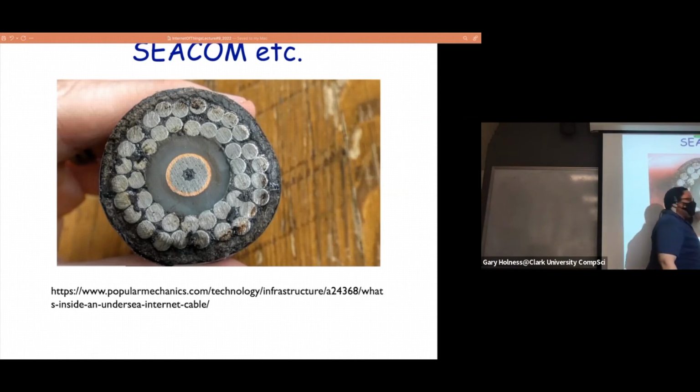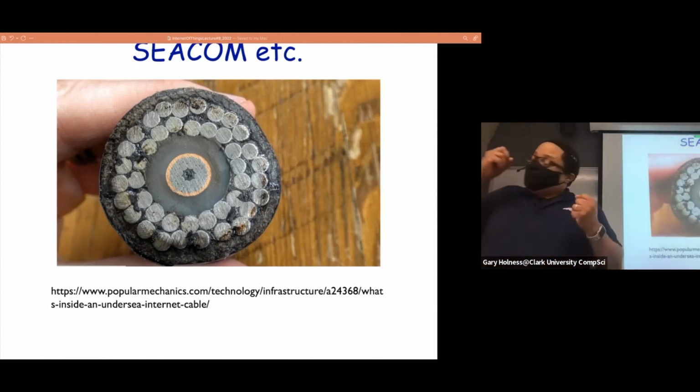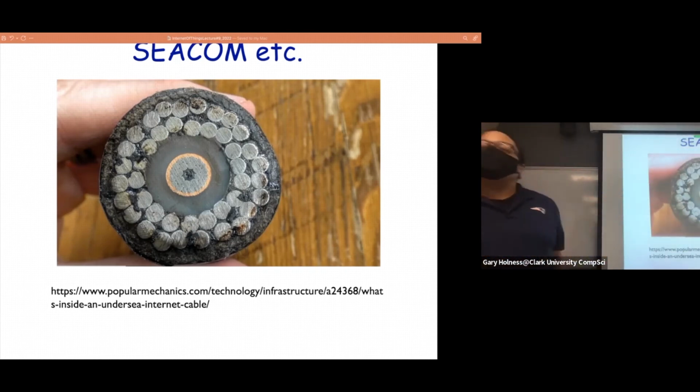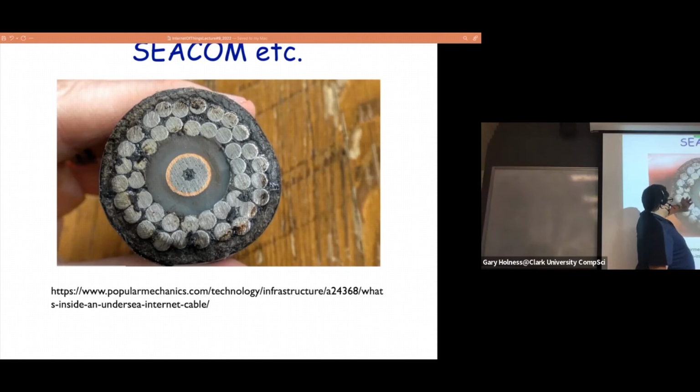And this copper sheet here, it also transmits power. And the reason for that is every, I think it's 1,000 miles or so, you need to amplify that light signal. Well, how do you power it? No one's going to go out there and install a battery or power source. So it's inside the cable. And so not only do you send these pulses of light, every so often you amplify them, you read the signal, and then you send it out stronger again. So it propagates thousands and thousands of miles from end to end. And so we have more tensioning cables to make it strong, and then a nice corrosion-proof, but not earthquake-proof encasing.